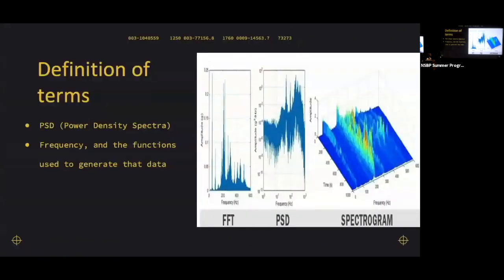Before I continue, I'll have to talk about the PSD, the power spectral density, and what it actually means. It essentially measures the power content of a signal against its frequency. Using Fourier analysis, any physical signal can be decomposed into a number of discrete frequencies, or a spectrum over a certain range. The statistical average of a signal analyzed in terms of its frequency content is called a spectrum. The data that you'll be seeing from here is essentially in that format.